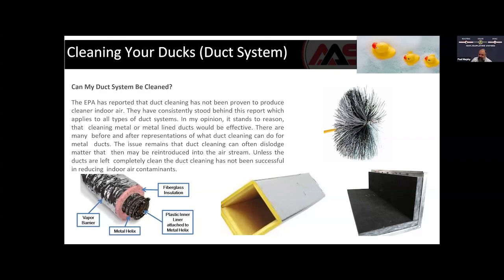I really don't see duct cleaning working in any situation other than if you have an internal metal lined duct, and you probably could get some dust off the walls of the ductwork. That's about it. Dryer ducts, those are great. It's great for cleaning dryer ducts because those fill with lint and that'll get all the lint out. But we don't suggest it on any of these types of duct systems that we see here in South Florida.